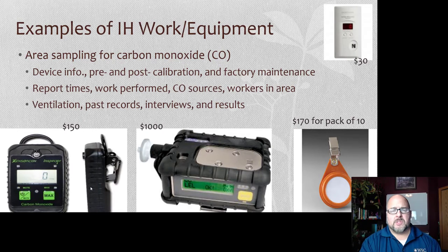Every house should be equipped with some form of carbon monoxide detector, because the burning of natural gas and propane gives off a certain low level of carbon monoxide. When a burner is not operating properly, or the exhaust system is not operating properly, you can have a buildup in the house. You want to keep it below 50 parts per million, hopefully a lot lower than that.